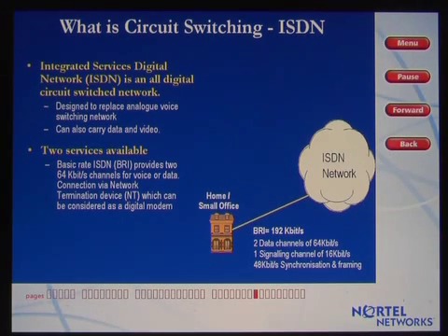There are two ISDN services available to customers. Basic Rate Access, or BRI, which gives an access of two B channels and one 16 kilobits per second D channel, with a total customer usable transmission rate of 144 kilobits per second, which is multiplexed over a physical 192 kilobits per second interface. The additional 48 kilobits per second is used for various framing and synchronization purposes and is not available to the user. B channels in the BRI can be used to carry either voice or data. The BRI is aimed at the small business, home workers, and heavy internet users.